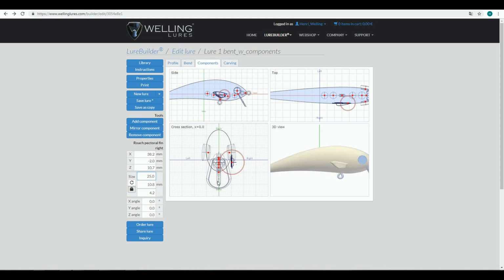It's quite decent. And then I click this point with my index finger to center the view, and then with my middle finger I'm rotating it, and you can see that it's now a bit out from the lure body. We can see it also here in the cross-section view. I'm keeping that in the position in the side view, but now first working with cross-section, turning that into the angle that this lure surface would demand. Click with an index finger and rotate that a little bit.